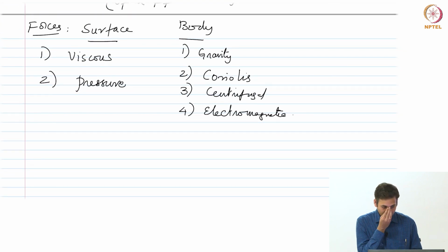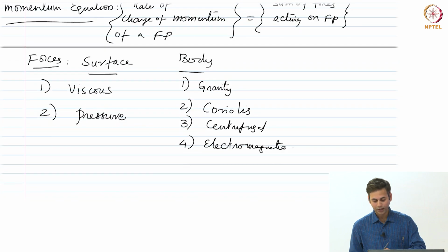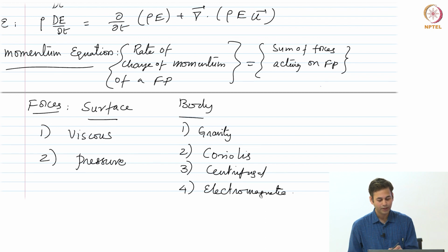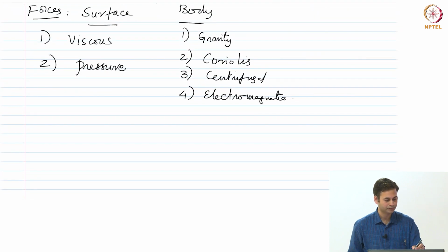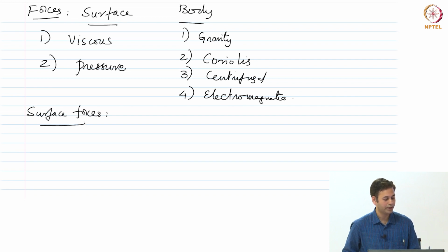Now we need to understand these forces such that we can develop the right hand side that we have in Newton's second law of motion. So we look at the surface forces first. The surface forces arise out of the pressure and the viscous forces that we have. In order to know the forces that act on it, we have to know what stress system a fluid element is subjected to.